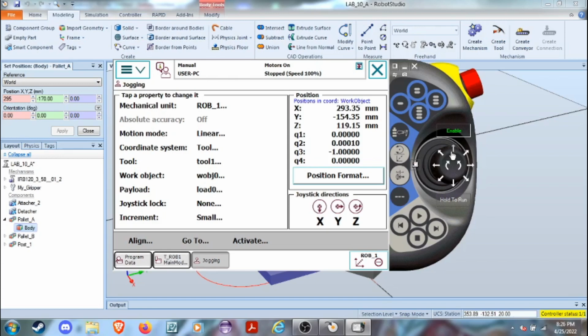We're also going to do the same thing with the Y condition. And while we could move our work object all the way so that it's at 0 on the base axis, we're going to adjust it so that it's 60 millimeters above where the 0 point is in the default work frame. So 295, we're going to adjust our Y using the larger increments.